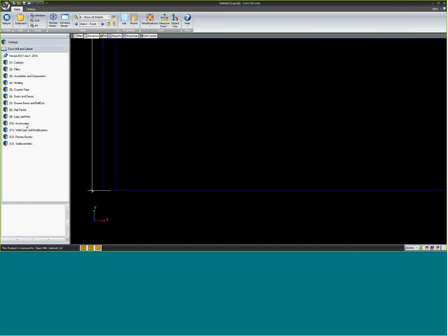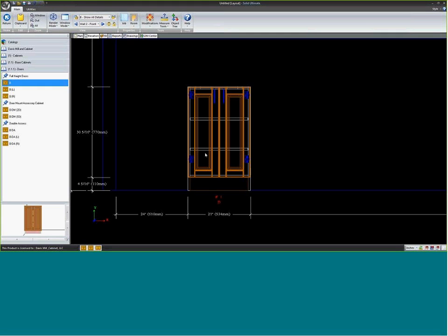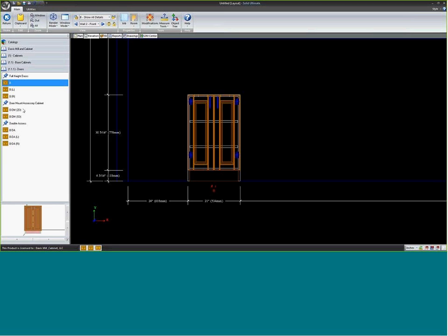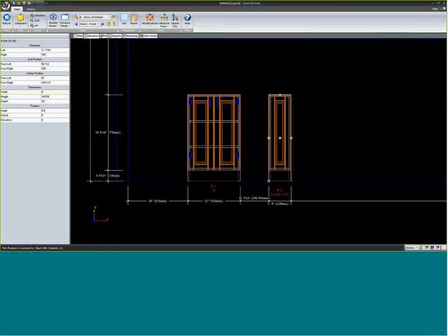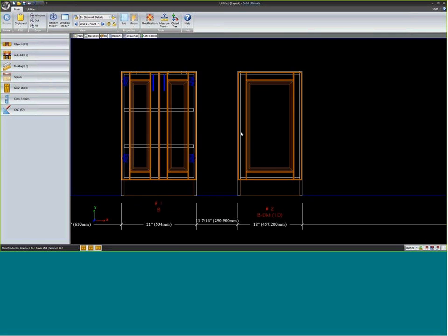Accessories and wildcards are two really commonly used things. Both of them require an object already to be out here. So let me drag a few cabinets out here to show you this. I'll put a base here. Let me drag out one of these two, a door mount accessory cabinet. Let's do a steel door. Make it 18 inches wide. Let's use that one as our example.